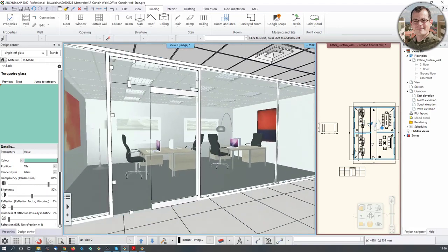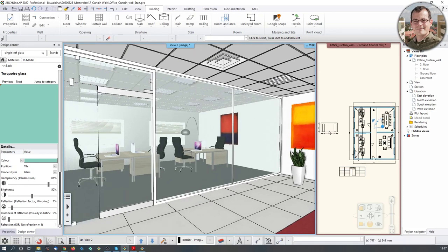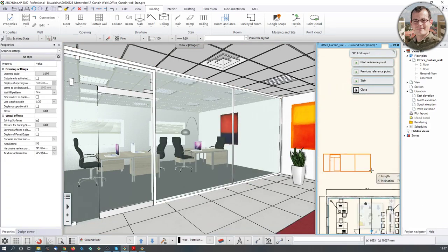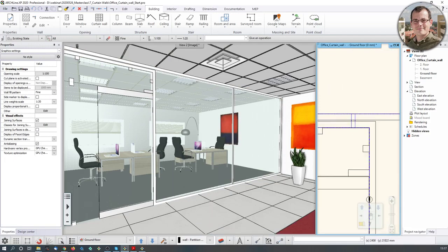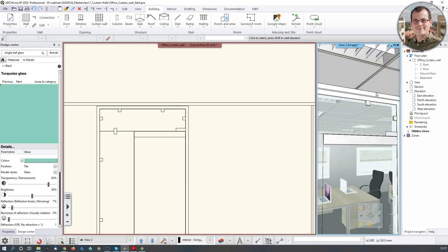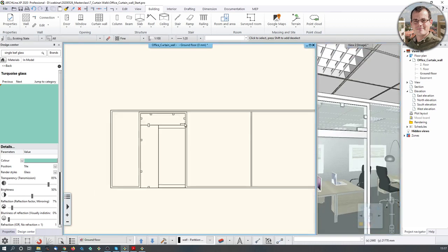So this should be like an executive suite with all these large glass surfaces. But again, there are some problems. Maybe you don't see it right away, but if you go into the settings, you would see that this is actually not done. So I have to go to the layout again and fine-tune this curtain wall a bit. If I right-click, I say edit layout, I see that there is an issue over there. So what is that even? That is actually one of the vertical divisions, which I'm not sure if you can see it in the 3D, but it's right over there, this tiny thing. What this means is that even though I don't see it, there's an extra vertical division. What do I do?